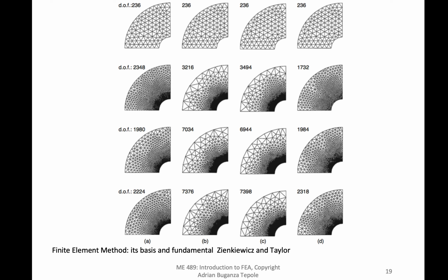You can use adaptive meshing. Abaqus has some capabilities to do that, where you start with some regular mesh and then it will refine the mesh according to the gradients. There's some error approximations that Abaqus can do to try to find where to refine the mesh. So that's something we haven't done, but that's something you can do. But again, you don't need to have a fine mesh everywhere. You can have just a fine mesh in the region where you need it.